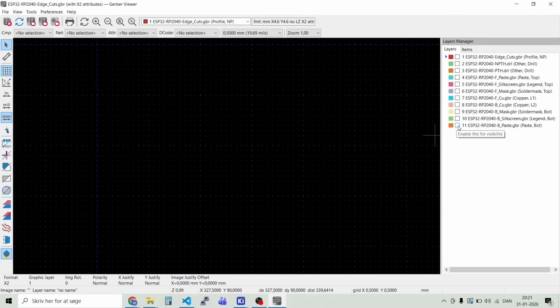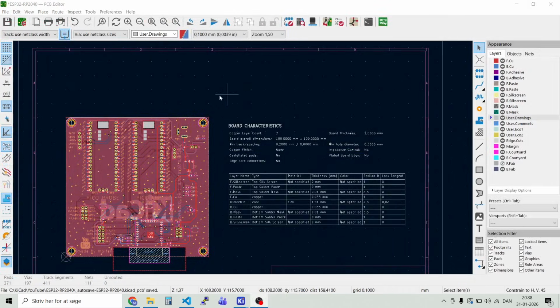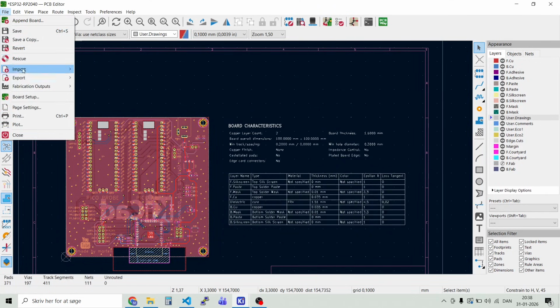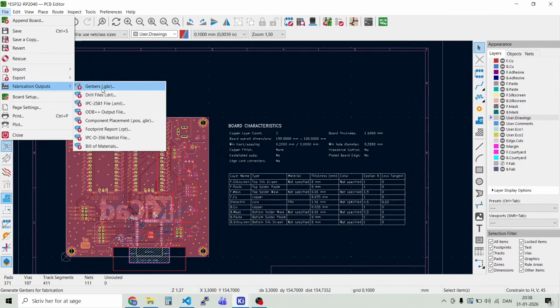There's nothing. So that's also a very helpful tool sometimes to have a look, but this is also integrated into KiCad, this Gerber viewer. And now we're in here in the PCB layout. We could also generate a few more files. So we could also generate an XY coordinate file, a component placement file. So this is this.